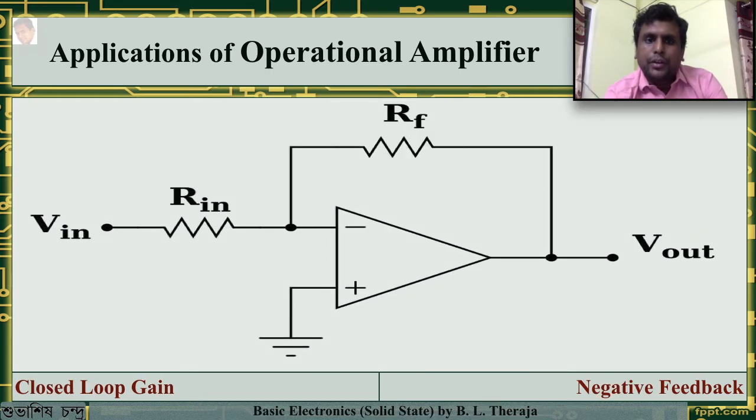So the op amp is operated with a negative feedback. In case of a negative feedback, a part of the output is fed back through a feedback resistor in phase opposition to the input. With negative feedback, the voltage gain can be reduced and controlled so that the op amp can function as a linear amplifier. The gain in this case is called as closed loop gain as opposed to the open loop gain in the previous case. Let us look into the operational amplifier's characteristics in case of feedback and no feedback.